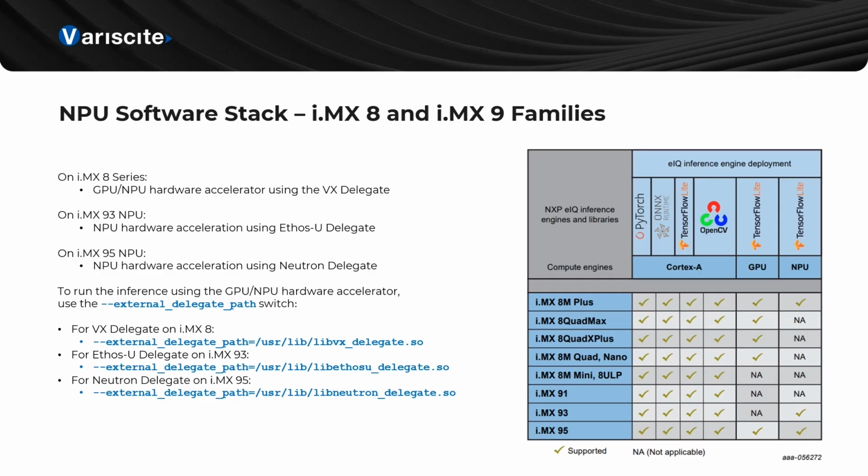The 8M+ in particular offers hardware acceleration on the NPU using the VX delegate. The i.MX93, although lacking a GPU, provides hardware acceleration on the NPU using the Ethos U delegate. And lastly, the i.MX95 supports hardware acceleration on both the GPU and NPU using the Neutron delegate.